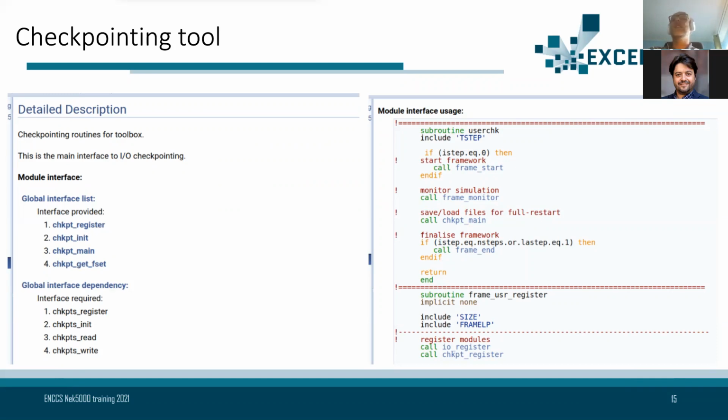However, the native way of restarting Nek5000 will produce only a single file for restart. This is, of course, very useful because at a given step, you can simply stop your simulation, write a plot file, and then start from that plot file. However, you have to be aware that the first 3 steps of your simulation after restart are not exact, because you increase the time integration order step by step. From the first Euler step, the second step will have second order, and the third step will be third order. So you simply slowly increase it.